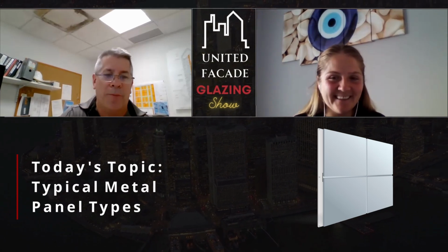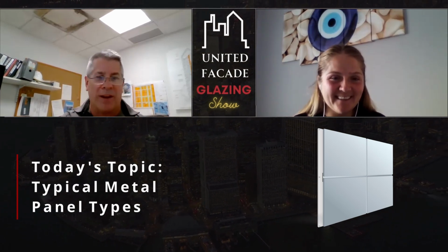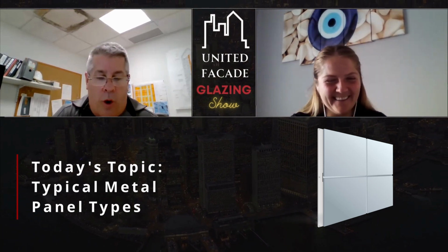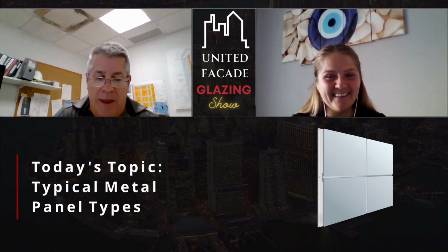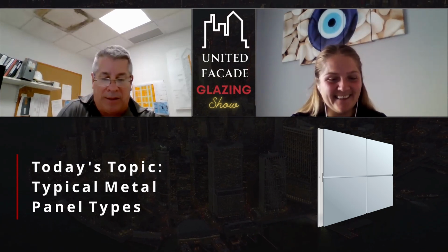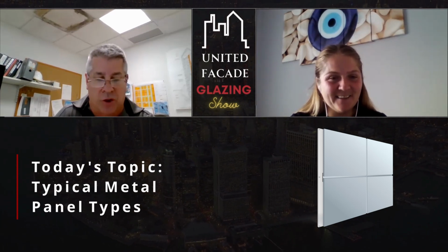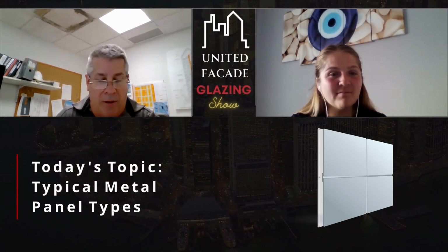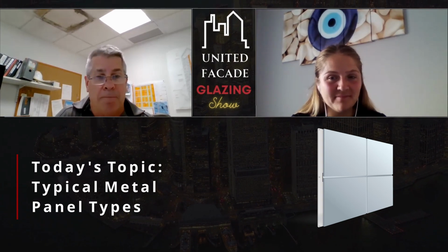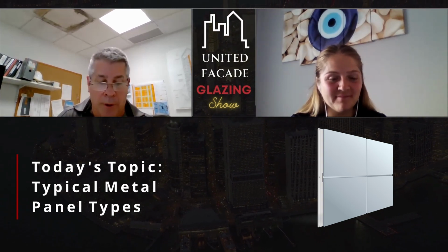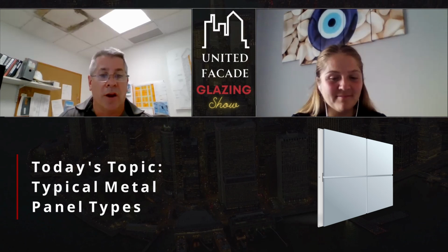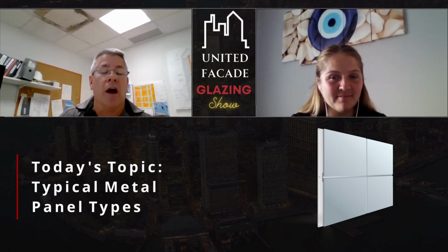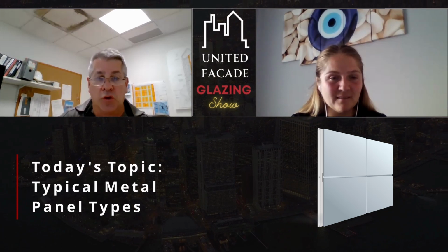And that's one of the biggest issues with architects. It needs to look perfect. It needs to look perfectly flat. With the core, because the aluminum is attached and glued to the core under high pressure, it's going to be very straight. As straight as your core is, as straight as your panel is. So when you go to a plate panel, whether it be aluminum, bronze, zinc, whatever material you might be using, or steel itself, the thicker the panel, the straighter it's going to be.